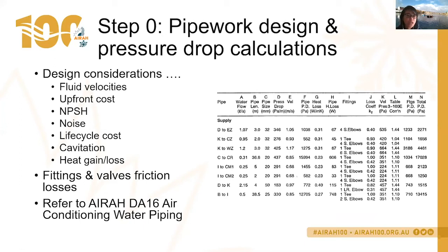When you are doing your assessments, you'll be considering your NPSH, or net positive suction head, that's required. You might be considering what the noise is in terms of how fast the velocity is flowing. You might consider the life cycle cost, so the cost across the whole life of a pump, 15 to 25, 30 years.